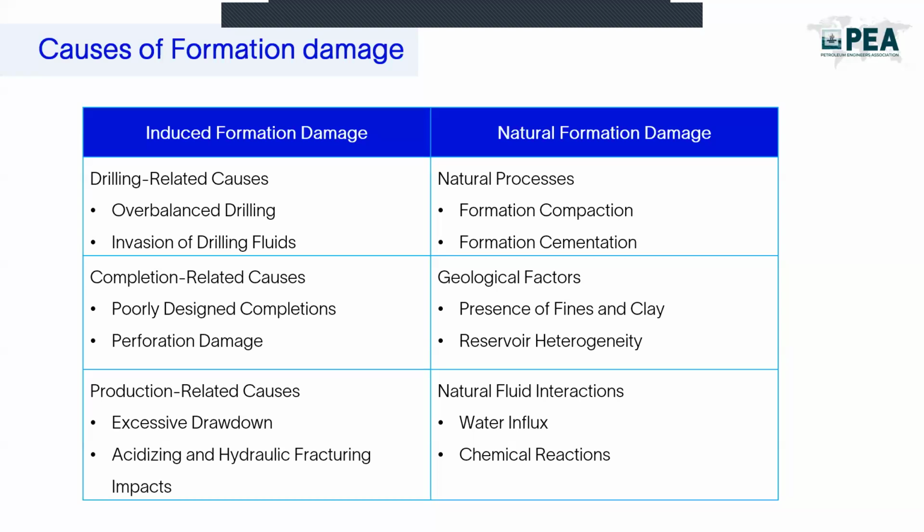Drilling with a hydrostatic pressure that exceeds the formation pressure can cause fluid invasion into the formation, leading to clogged pore spaces and eventually reducing the permeability. And here, when I say exceeds, I'm saying it up to a limit.